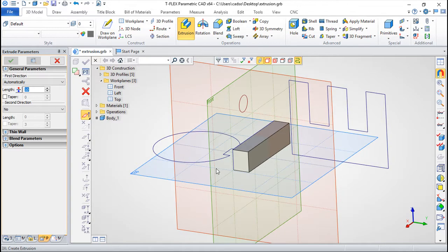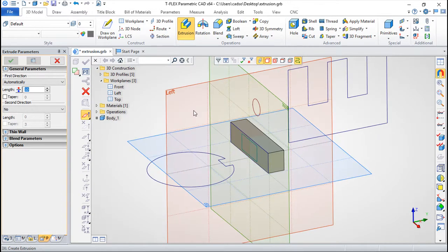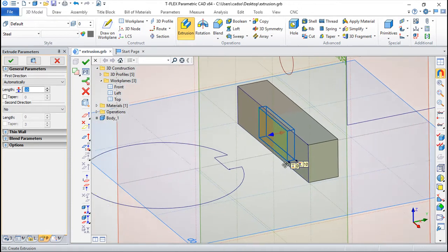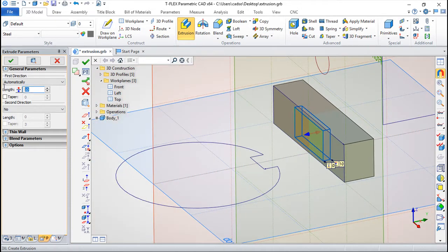I can do also, and this is a normal extrusion by the direction, the normal on the contour. I can do also an extrusion now. Instead of saying or mentioning what I want through these draggers, I can simply define the distance here, and I can define the direction. If I click here, it changes, okay?